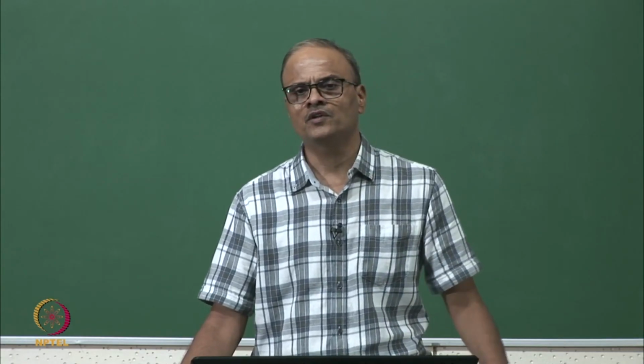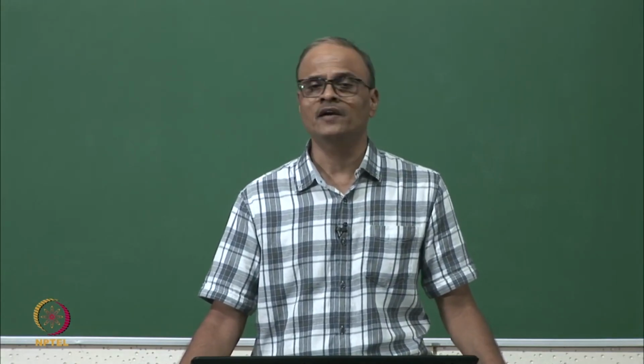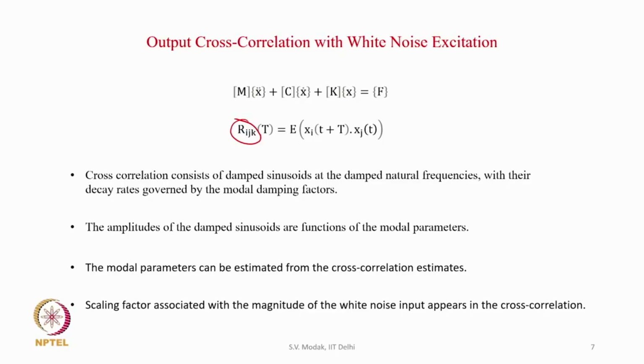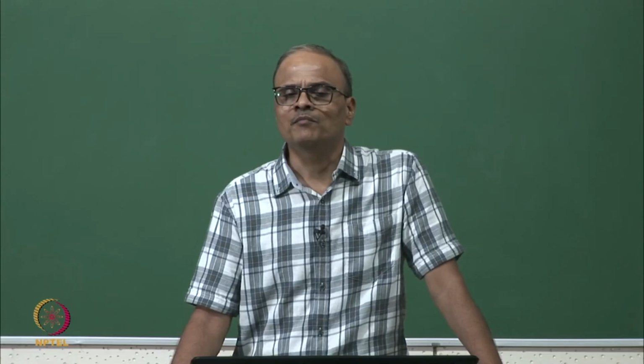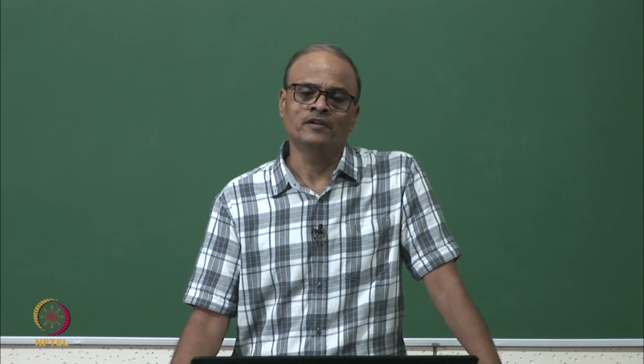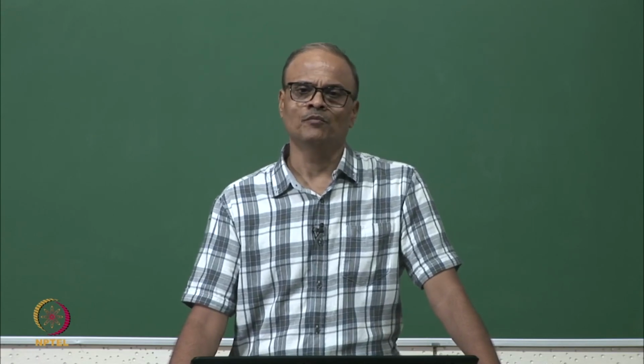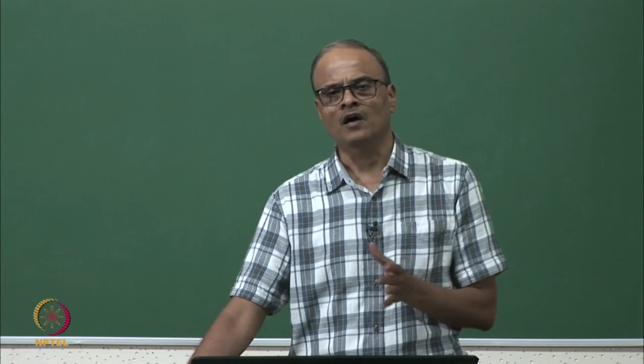One consequence of the lack of information about this scaling factor is that the mode shapes obtained by operational analysis are unscaled, right, they are not mass normalized as we obtain in case of experimental analysis. So, the mode shapes are associated with an arbitrary scaling factor.